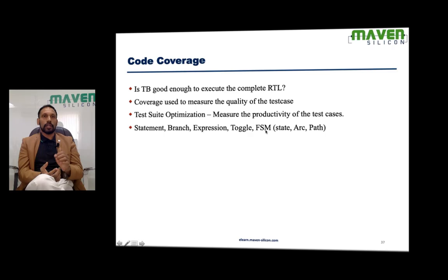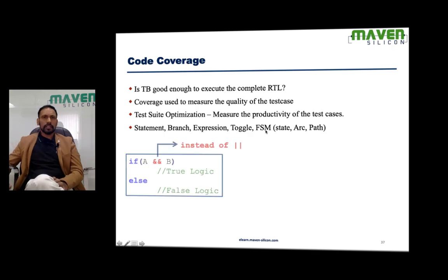During simulation, when you activate the code coverage option, obviously the simulator is going to generate all kinds of coverage information. You would be able to even choose the metrics also, whether you want to generate statement or branch, or you want all kinds of coverages. All right. Look at this example. Sometimes it helps you to find the design issues also.